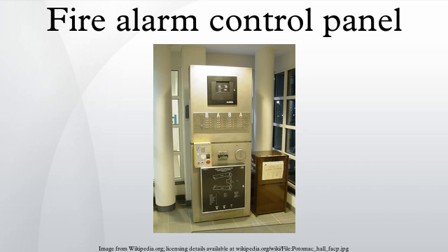Each device on a SLC has its own address, and so the panel knows the state of each individual device connected to it. Common addressable input devices include smoke detectors, heat detectors, manual call points or manual pull stations, notification appliances, responders, fire sprinkler system inputs, switches, flow control, pressure, isolate, standard switches. Addressable output devices are known as relays and include warning system bell relays, door holder relays, auxiliary relays.